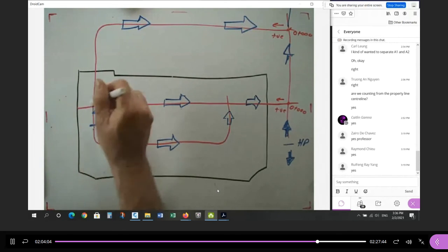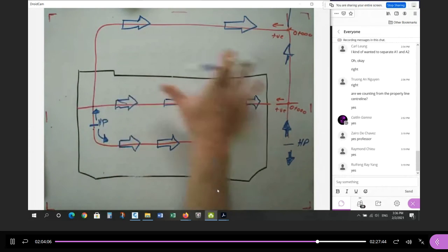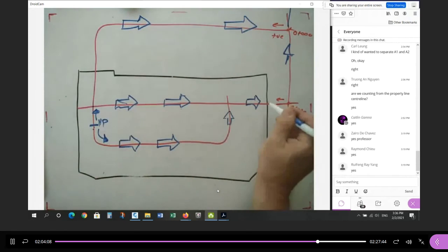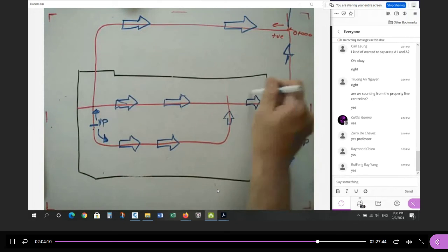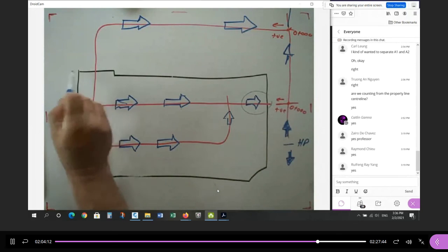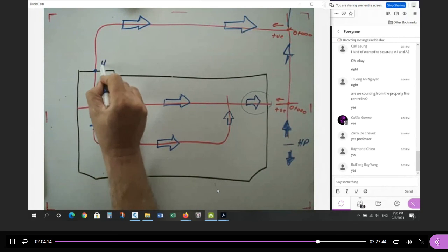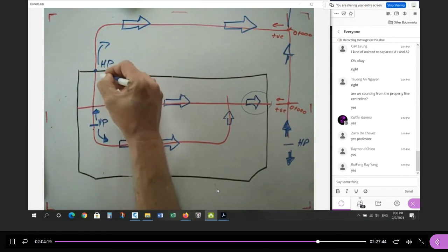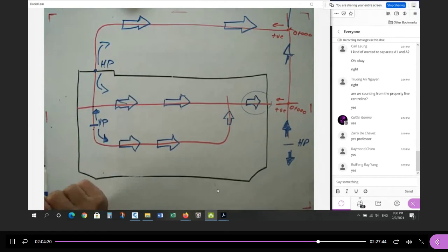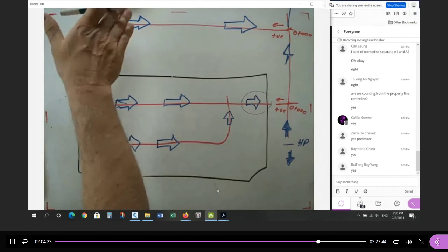Okay, this way and this way. On this road here, remember the entire area of our subdivision was supposed to come out here, right? The outlet is here. So really there should be a high point as close to the intersection of the property lines here. So this wants to go this way. This should stay in and go that way. The route is important. I don't want to put more water this way.